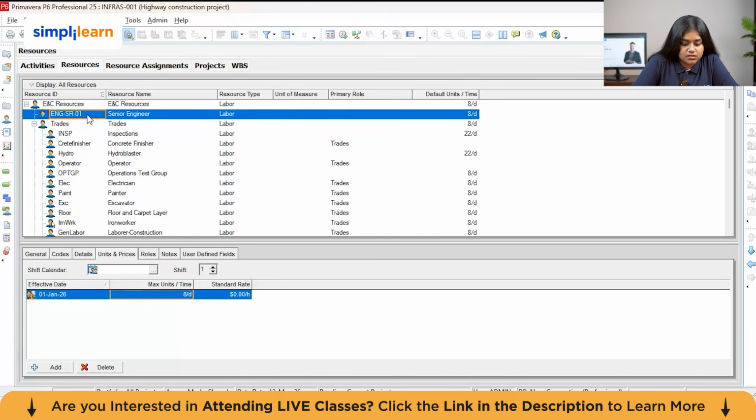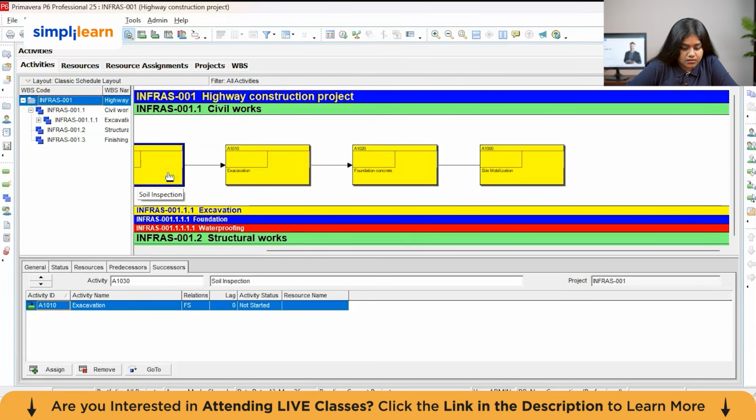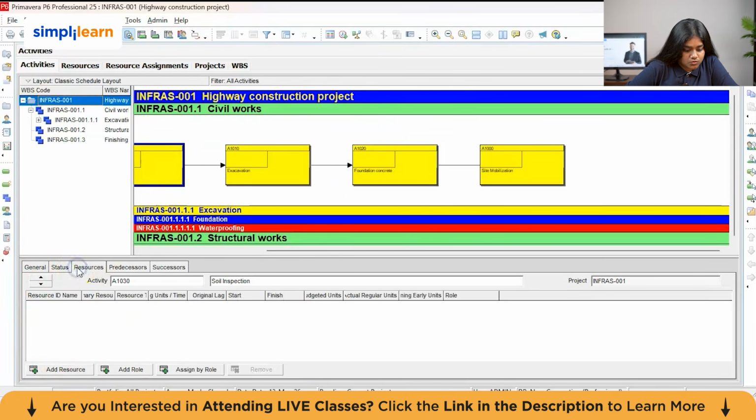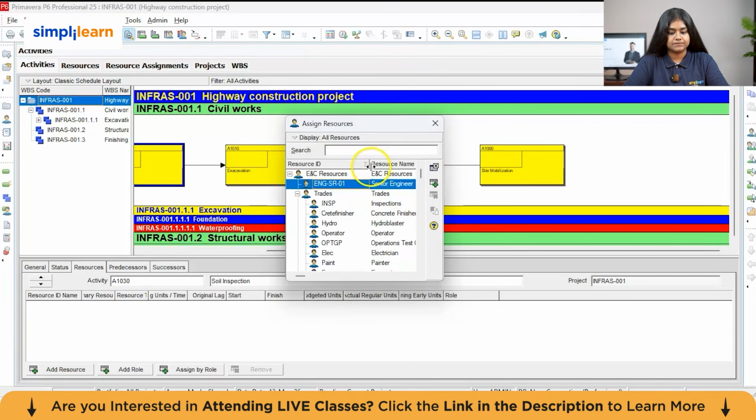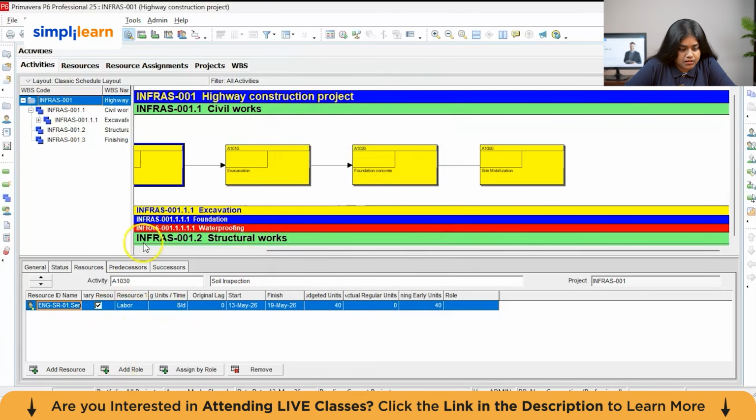We have to assign resources to the activities. So these resources are created, we have to assign them to the activities. How to assign them? We have to go to the activities window and then select an activity. Here in the resources column, we have to add the resources. So we can assign them here. Like that, we have to create resources for all the activities and assign them there.